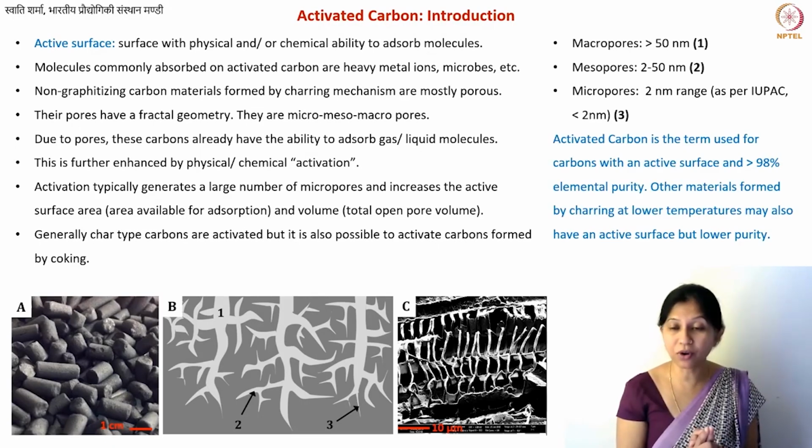Now, one more thing, as I'm using the terms porous carbons and activated carbon interchangeably, but they are not the same. Porous carbon is the carbon structure that you get after the charring process. But when you further do chemical or physical activation and increase the number of micropores, that is the activation process. However, industrially, the term activated carbon is used when the purity of the carbon is also high enough.